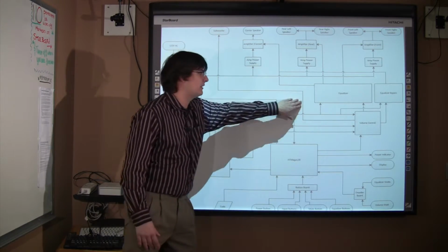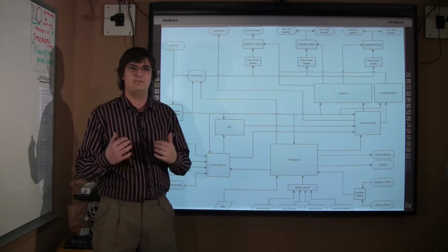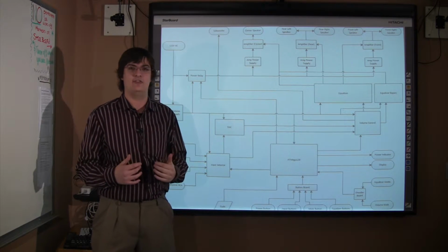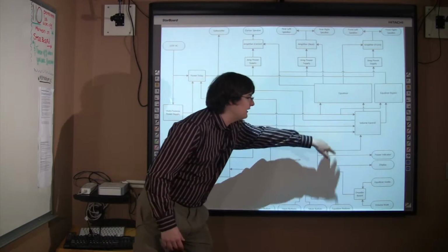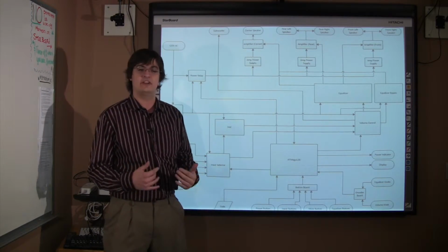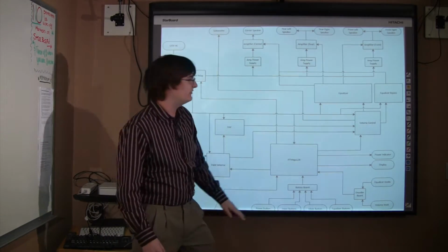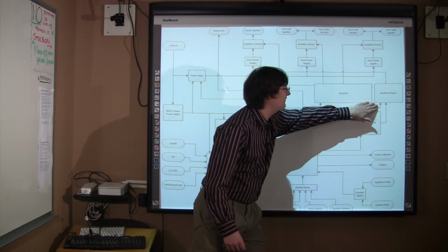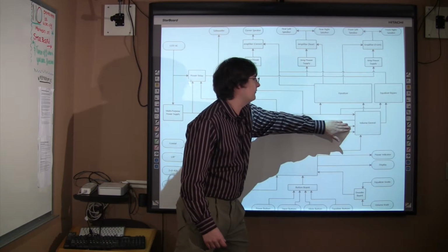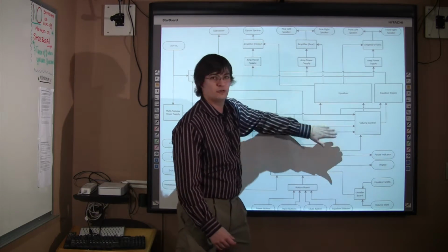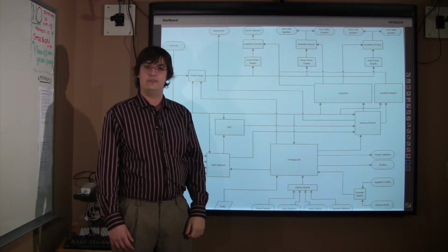The equalizer block controls the signal's primary frequency bands and attenuates the gain at those specific bands, whereas the volume control block increases or decreases the volume of the signal as a whole. The equalizers can be bypassed using our equalizer bypass block, which drives the signal out of the volume control block straight to the amplifiers to increase signal fidelity. Now to Jesse with the digital controls.